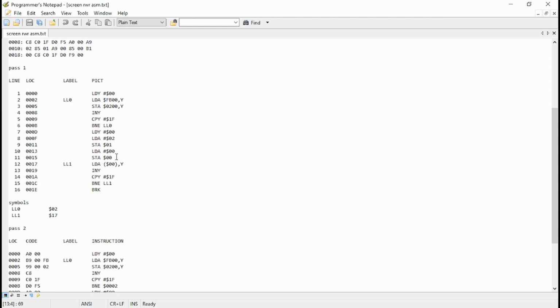And the reason why we do that is when we do this indirect indexed addressing, we pass it a value of the zero page, which is kind of like a pointer, and it's going to retrieve an address from that area and one above it. So it's going to take 0100 and make that into an address. Now we've just fed into it 0200.